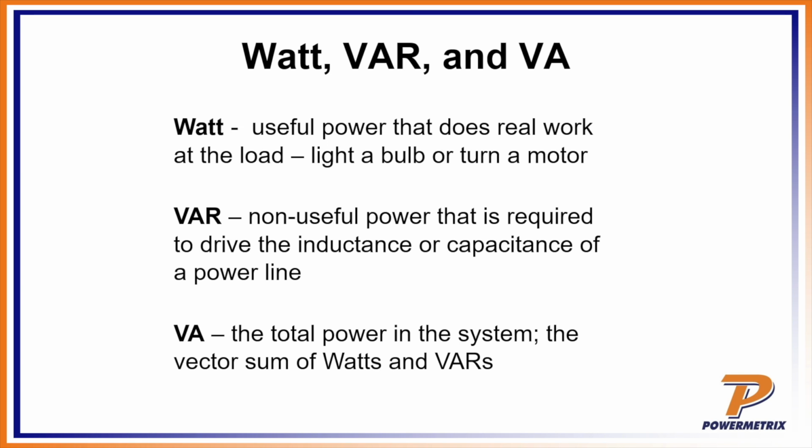A lot of the more modern loads that we have are not purely resistive. There's either a capacitive or inductive element to that. As we add more capacitance and inductance to the load, we start to generate a different kind of power, which is the volt amp reactive, or VAR. This is not useful power in that it does not do useful work. It's not lighting something, it's not turning a motor, it's not doing things that we as the consumer ultimately want to pay for.